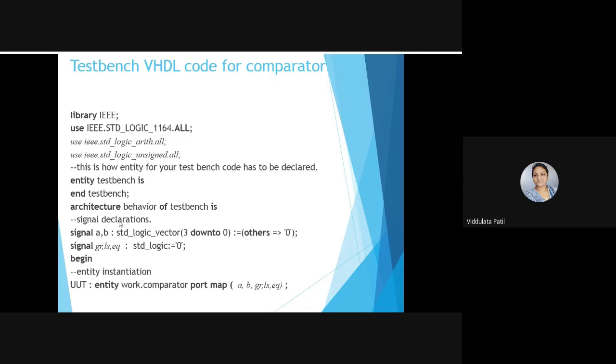After that, whatever signals are present in this test bench, we need to declare. So what we have to do is first declare the component, and after that, the signals in this test bench that we need to assign.